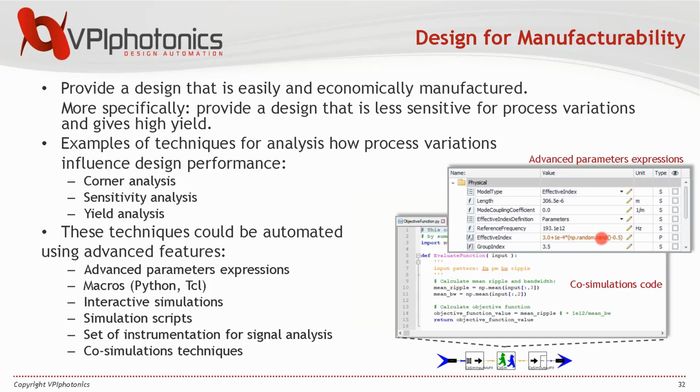However, if we need to change many parameters, even for our small example we already have about 10 components, and for 10 components you do not want to do this manually. That's why we need macros. It is just routine with scripts, which could help us to perform it automatically.